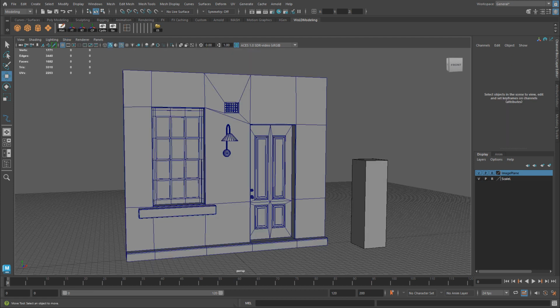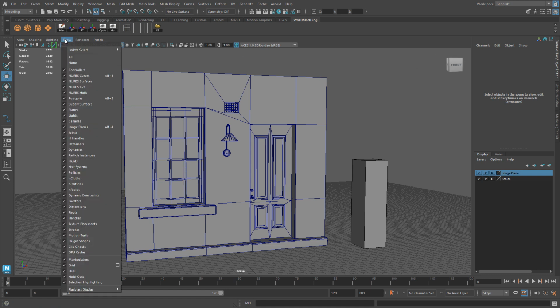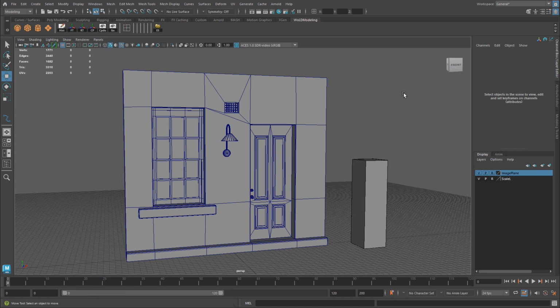Number 15, objects disappear or don't show up inside the viewport. And you can see that the visibility issue with anything inside the viewport that's supposed to be there but isn't, is a very common beginner problem. So in this one, it's about objects not showing up when you know they should be there, or whenever you create something, nothing shows up. There are a couple of shortcut keys that enable and disable object visibility. So if you already checked under Show and everything is checked on, and everything is supposed to be showing up, then there are a couple of shortcut keys that you may have pressed in order to enable or disable visibility of certain objects.